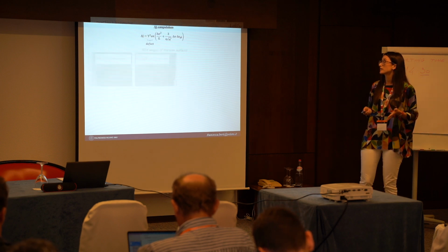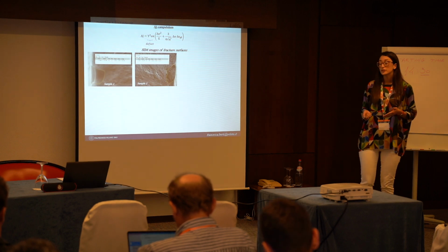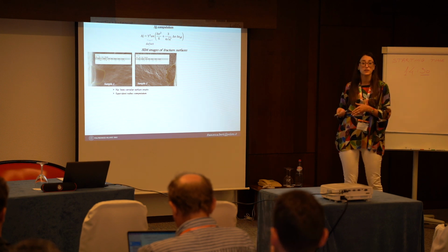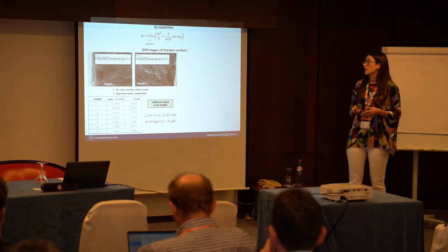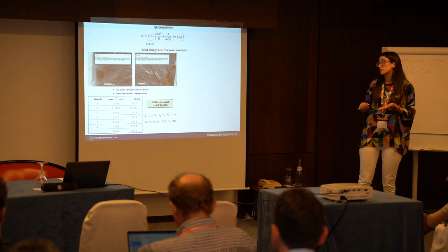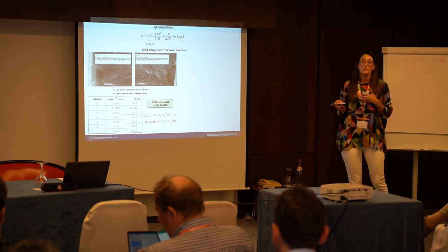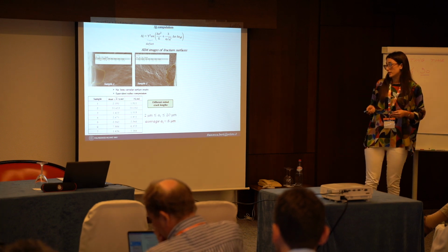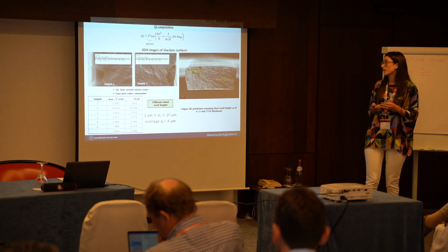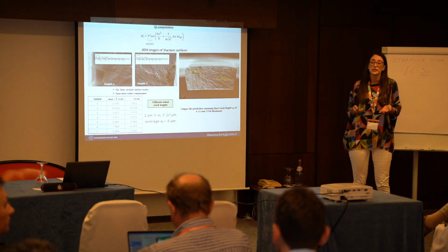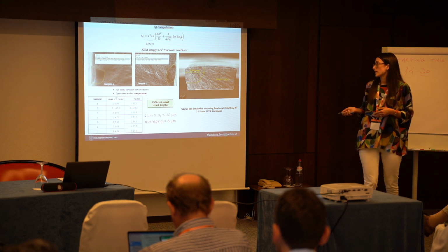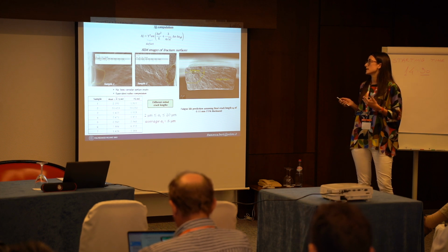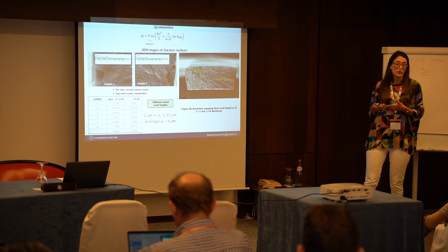After that, moving on to the defects, we did some imaging observation, and we were also able to make the hypothesis that these defects were semicircular on the surface. From our measurement, we were able to identify different crack lengths from 2 microns to 20 microns as the initial defect size. As for the final dimension needed for fatigue prediction, from observation we set 150 microns, which would be a reasonable measure, but this value is not influencing the prediction much.